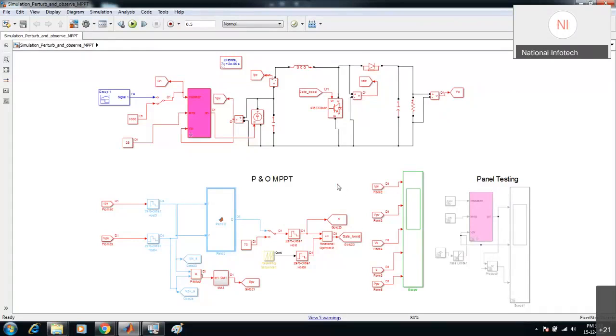And the same thing we can do with STM also. Yes, exactly. In order to lower the computational load and get the best out of the controller, you will have to select the timing very carefully. Then what are the parameters by which we can select the timing? So for that, we have set your carrier frequency to 10 kilohertz.